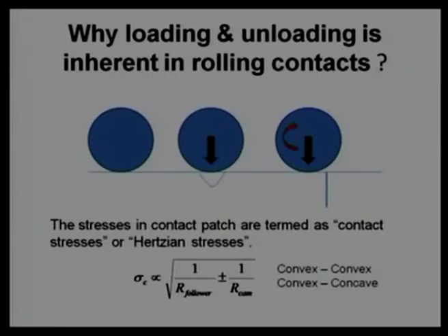And if it is a continuum, the direct load, or we say the point of contact or line of contact, directly comes on top of this point, then stress will be maximum. As it is continuously rotating, it will move away from the point, stress will reduce. Again it will move away from the point, further stresses will reduce and finally it will come to 0. So, just because of the rolling action, the same point is subjected to 1x unit of stress, 5x unit of stress and 10x unit of stress.